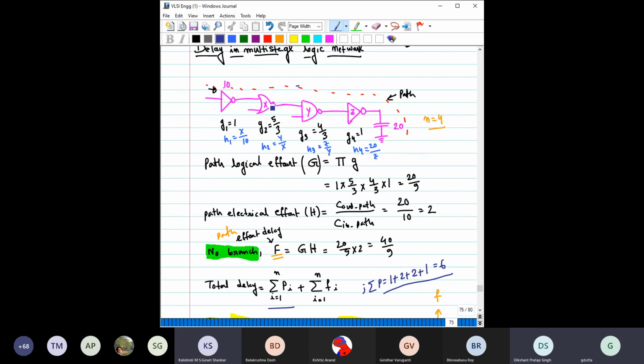So now we have to find the value of X, the value of Y, and the value of Z. After that, we also have to find the PMOS width and NMOS width for this, and the same for this and this. Because while designing, you have to design at the transistor level, so it is the PMOS width and NMOS width that will matter. So let us now complete that for this circuit.